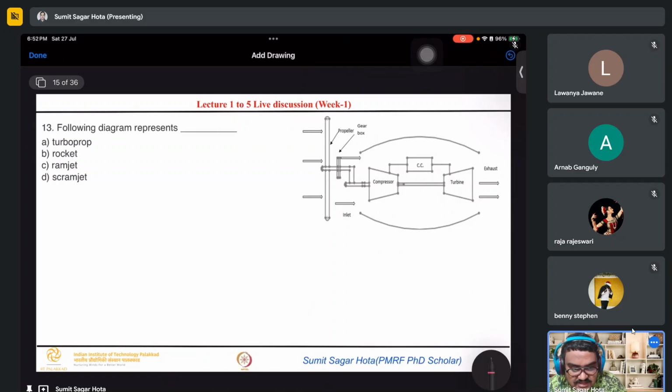That means through the turbine which drives the shaft, the compressor will rotate, and because the compressor rotates, it will rotate the gearbox. Because of that gearbox, it can enhance the rotation, maybe 1 to 5, 5 to 1, whatever the gear ratios are, due to which the propeller can rotate 5 times or 10 times more speed than the compressor rotation.